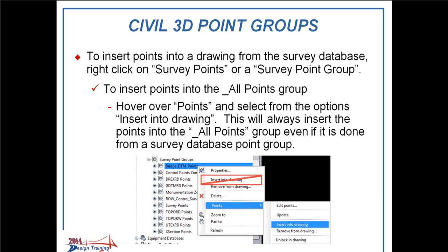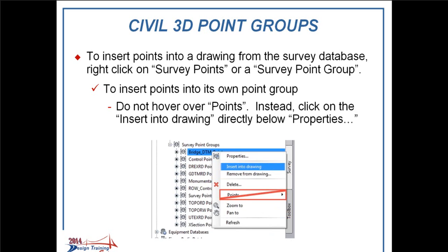This will always insert the points into the all points group, even if it's done from a survey database point group. Conversely, to insert points into its own point group, you do not hover over the points. Instead, you click on the Insert into Drawing directly below the properties.